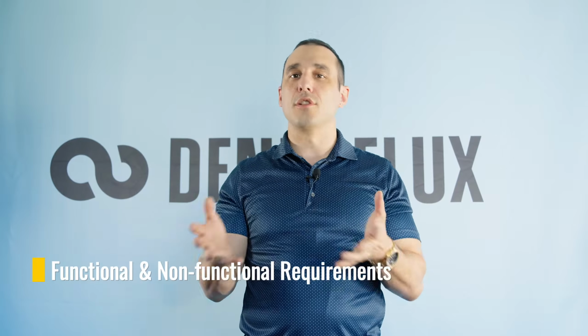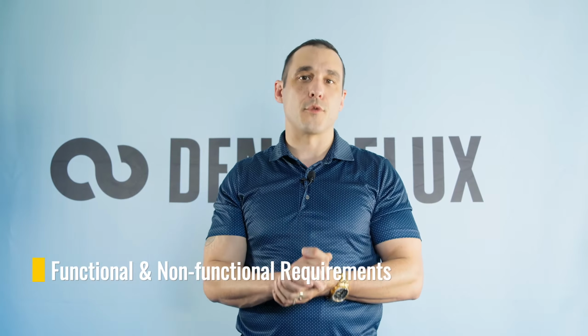The next high-level area that we would need to look at in an EMC review looks at our functional and non-functional requirements for the product. Functional and non-functional requirements are compiled into a product specification, and if you saw our earlier video about the 10 common EMC challenges, you will know how important a product specification is. This document often contains testing requirements and EMC standards compliance requirements that are applicable to your product.